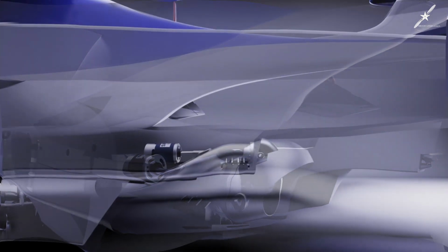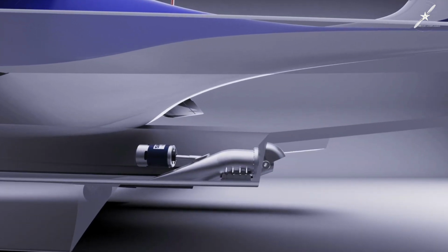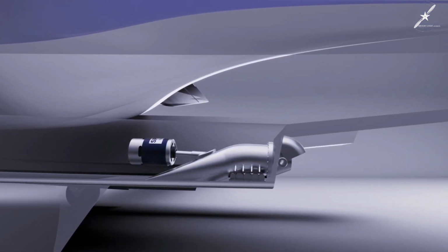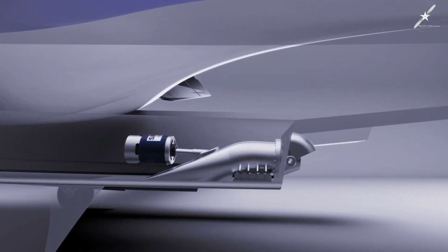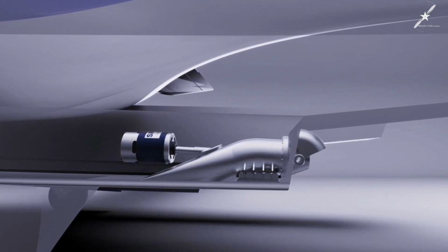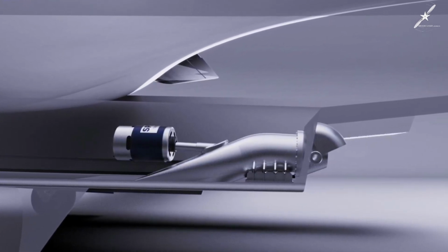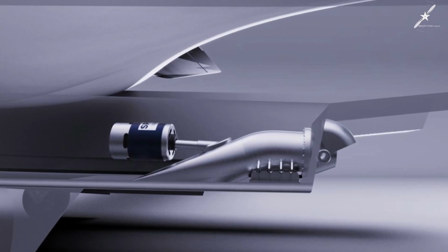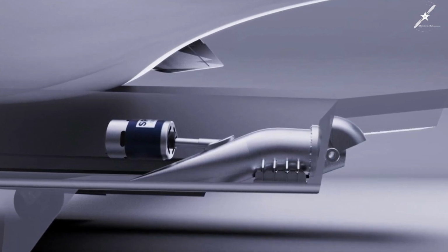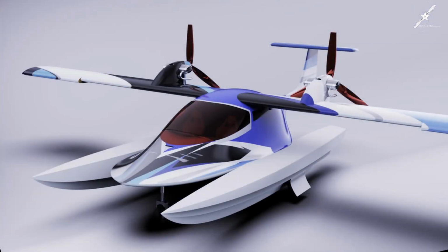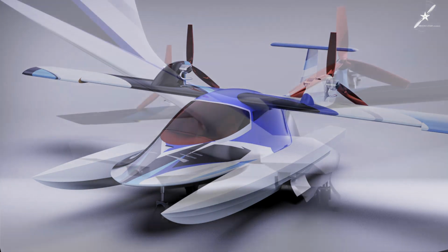Another neat feature of having thrusters on each pontoon would be that it allows you to spin the aircraft basically in one spot. I've already been asked if these thrusters would be used during takeoff. My first thought is no, but I have not completely ruled it out. I'm always thinking about safety, and if one of these jet thrusters failed while on takeoff, it might cause the aircraft to swerve. I see too many things that could go wrong trying to use them in conjunction with engine power during takeoff. But we'll take a look at this during our flight testing.